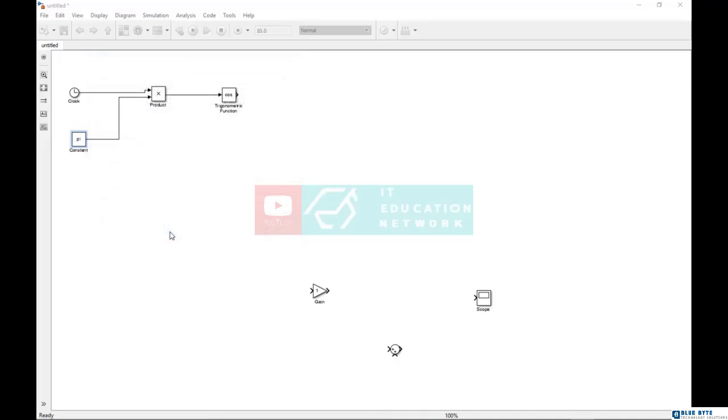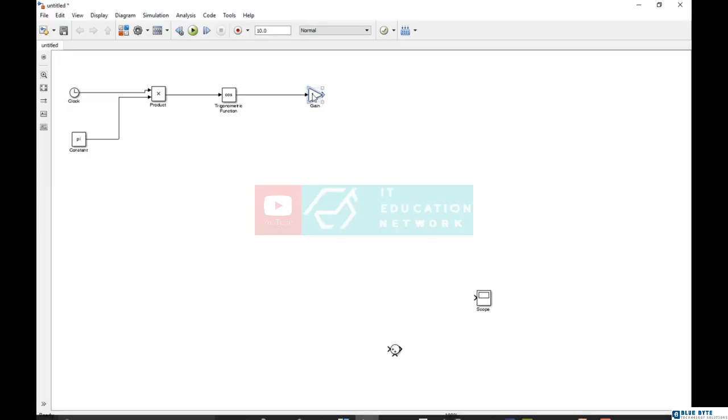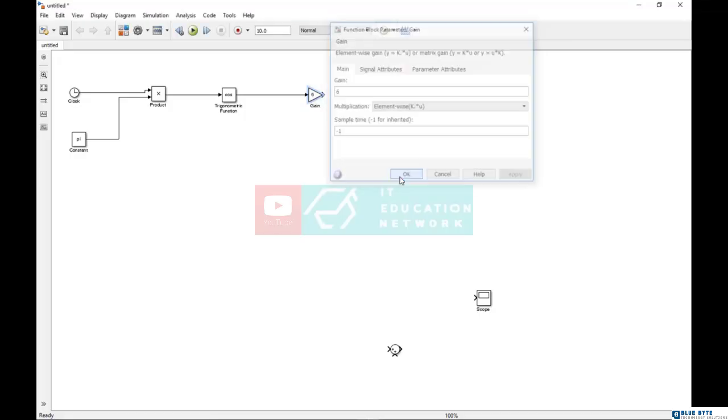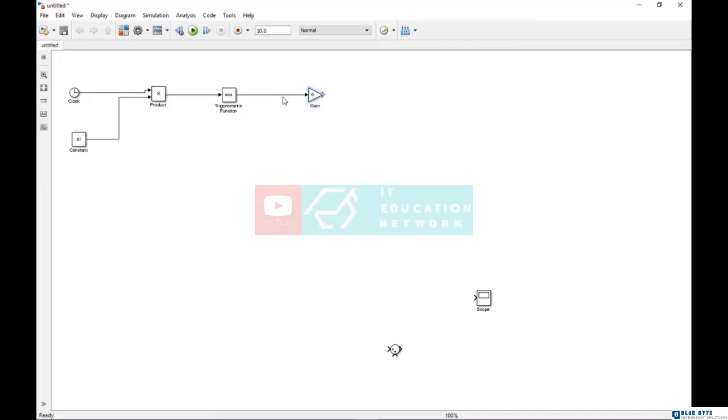We set the constant block P, so cosine multiplies to a gain, where the amount of gain is 6. The cosine is prepared now. For cotangent, as I said, we don't have a cotangent function in Simulink. In order to make it, we should use the mathematical equations of cotangent. As you know, cotangent equals cosine divided by sinus.